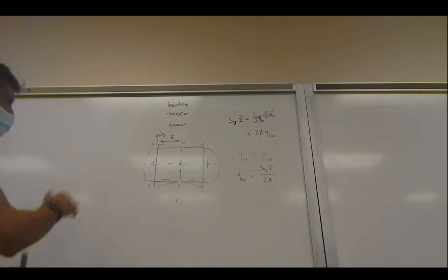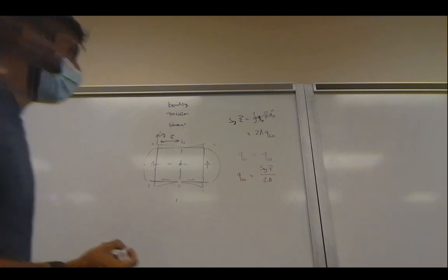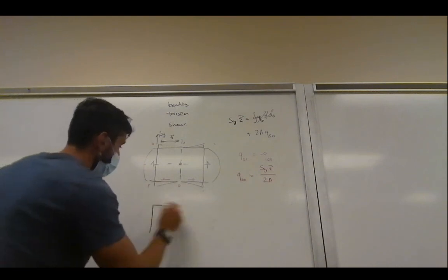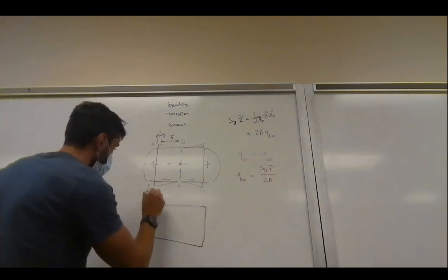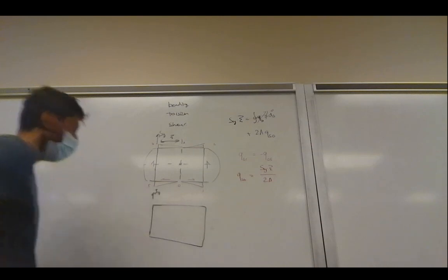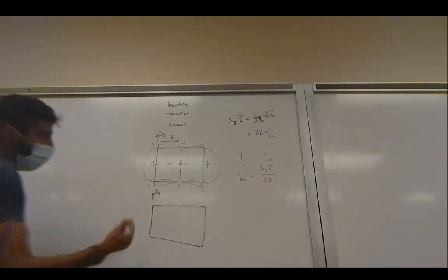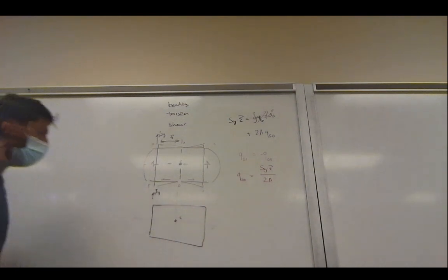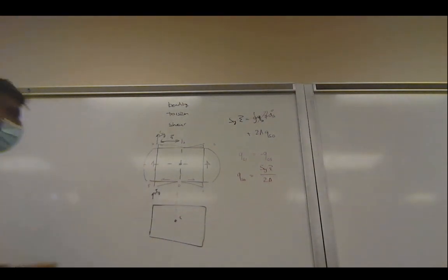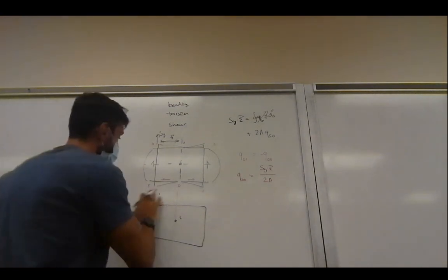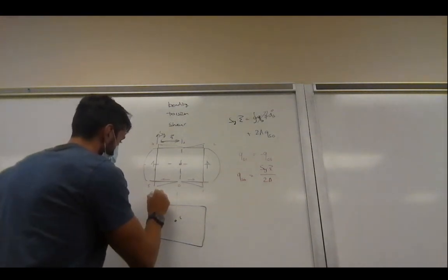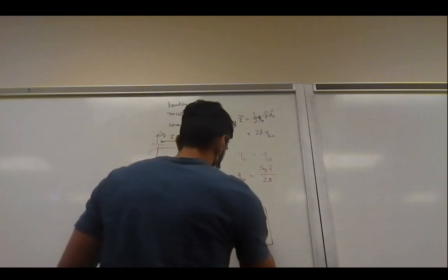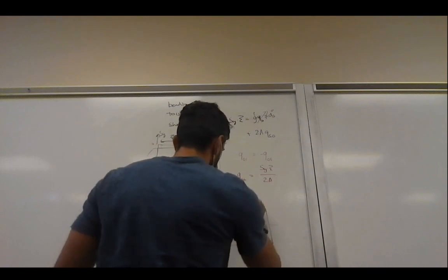So what we can see is that this is a simple problem, so it doesn't make a huge impact, but for more complex problems we can say, well, if we have this problem again, where Sy is like here, because this is, say, a double symmetric beam or cross-section, we know that the centroid lies in the middle. So we know this is the centroid. So what I can do is decouple this problem into a problem where our shear force Sy is acting through the shear center.